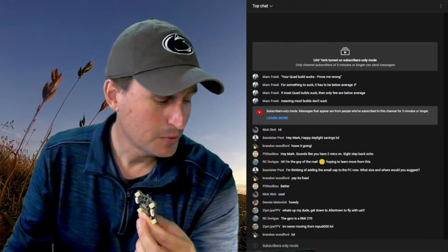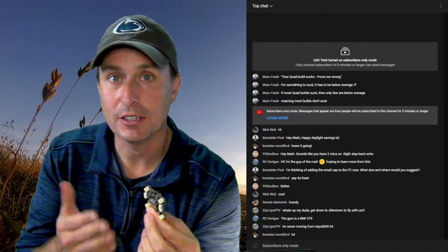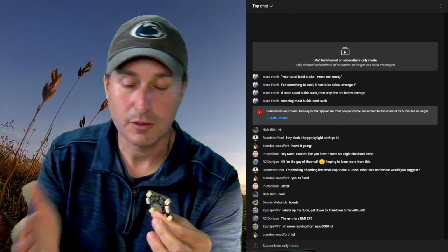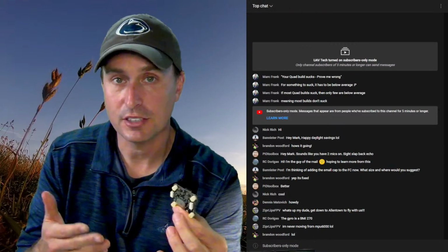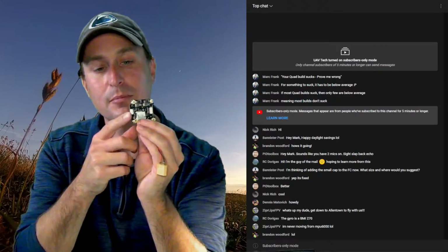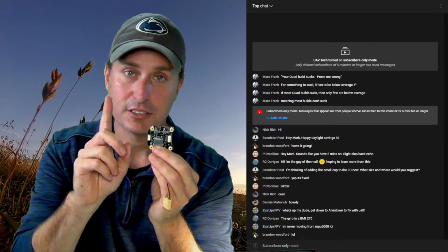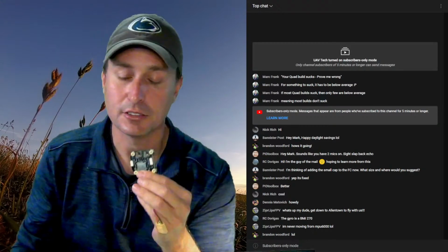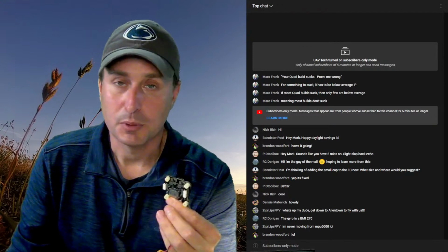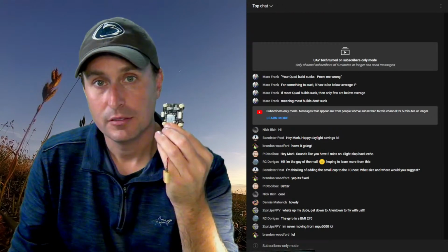If you have a little 2S or 3S pack, you could throw it on there. If you have an XT30, it doesn't need to be a big battery. You'd power your quad up with the 6S or 4S, and then you'd power your flight controller up with this little plug. Between the ESC and the flight controller, you don't want to take away the ground wire, just the VBAT wire on the connector, which is critical, or obviously you'll have issues. You'll burn something up. But that will then feed your flight controller with a separate battery.